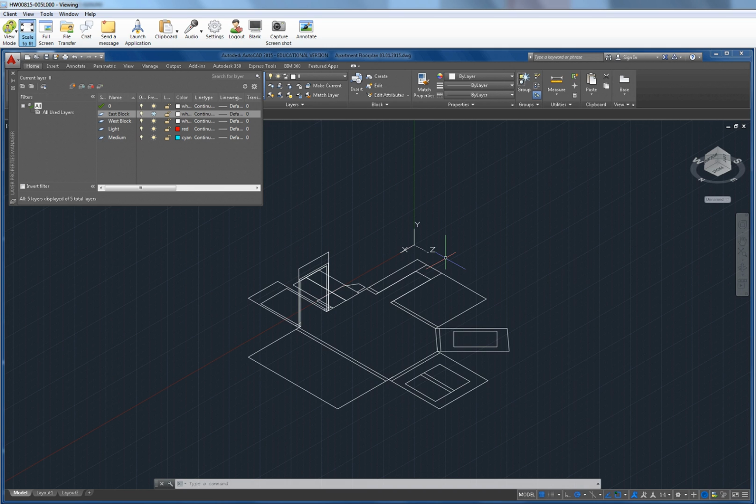I don't understand how the Z-axis comes into place because I only use X and Y. So if we're working in plan, the Z is always up, right? If we're working in elevation, Z is always out from the wall. So say we're drawing on that wall. This would be X, parallel to the ground plane. Y would be perpendicular, and Z would be coming at you.